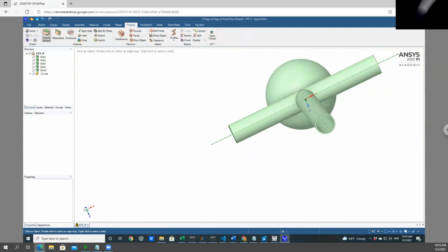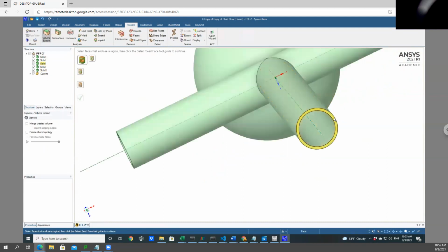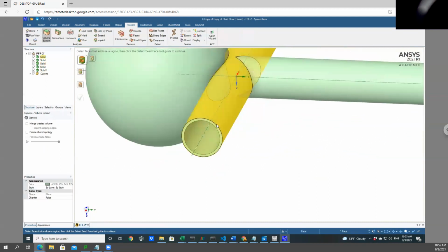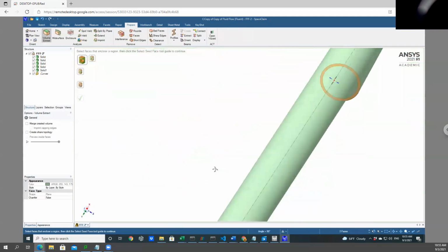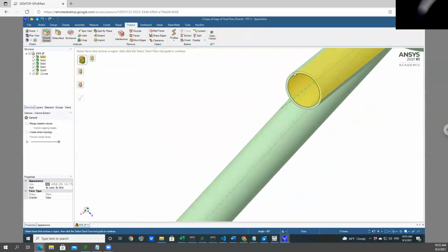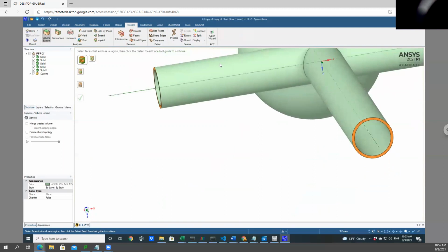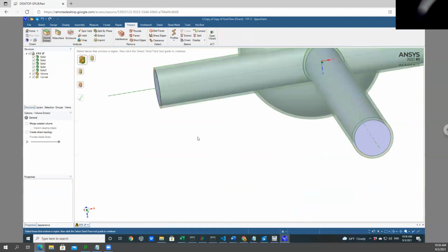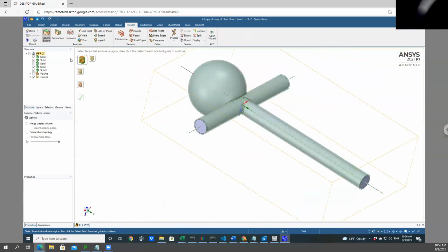Extract the solid. So click on prepare, click on extract volume, and click on your faces that enclose your region. So click on this one, control, well, first rotate, then control, left click, rotate, control, left click. So we are done with selecting our enclosed spaces, and now select your seed face, will be this one, the interior one, remember, and then click on complete. And guess what? We have our aneurysm.